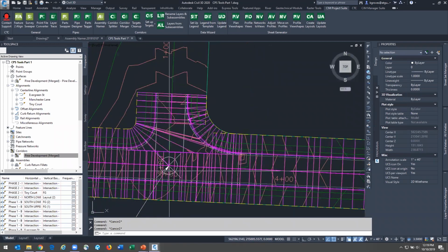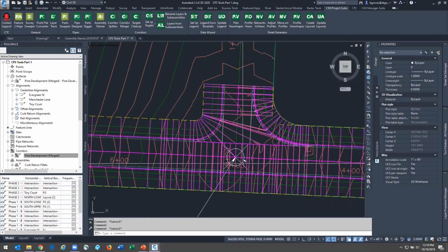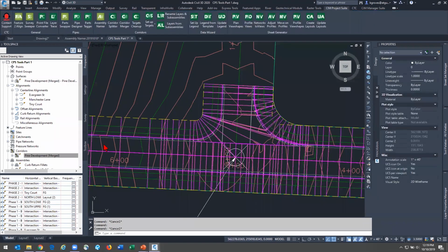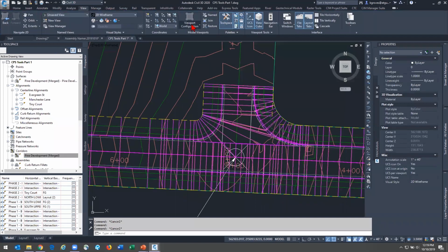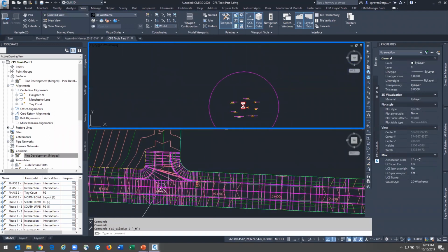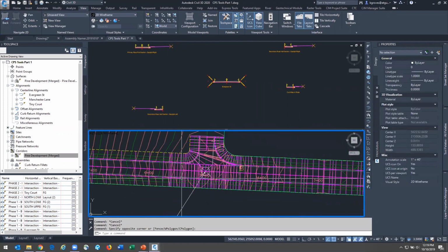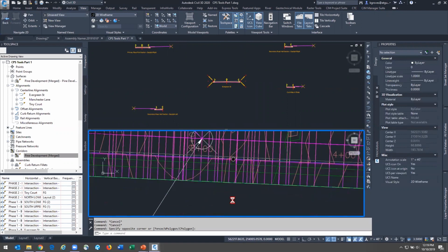And speaking of another way that we can use the corridor toolset is this whole concept of targeting, right? So when I use a target on my corridor, what I can do is I can say, hey, I've got my typical cross section, but sometimes our cross sections aren't so typical. I'll come up over here, split my viewports, go check out these areas, and I can see that this intersection down here doesn't quite look right.